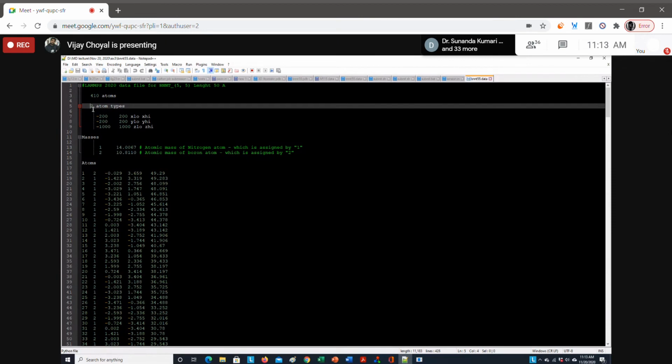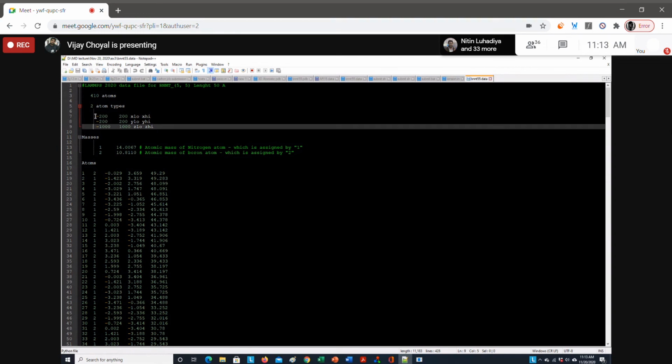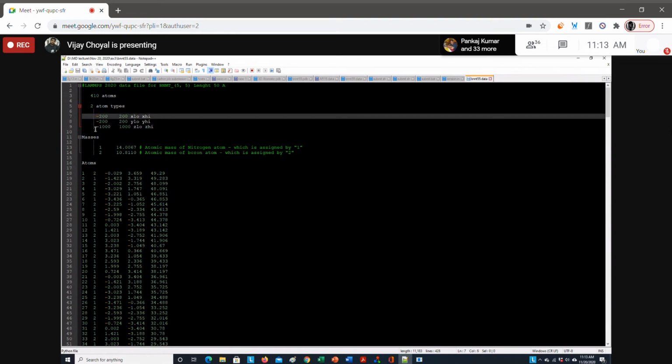Then we have to define the simulation box. From the universe we have to separate our system, so we define our simulation box. We have to define the simulation box in such a way that during deformation our system should not cross the boundaries.